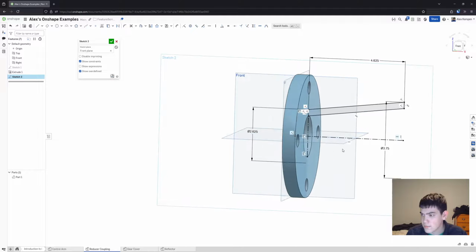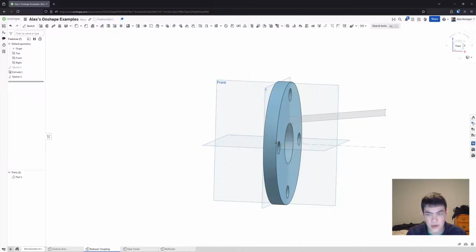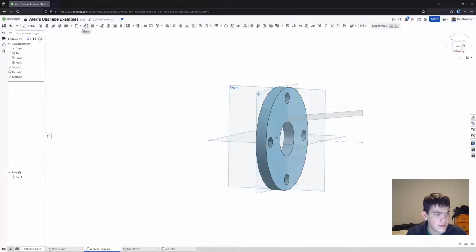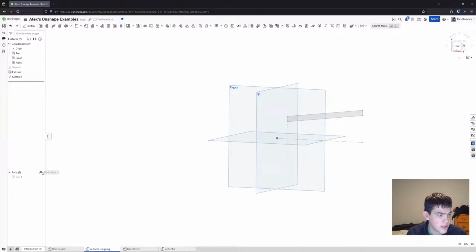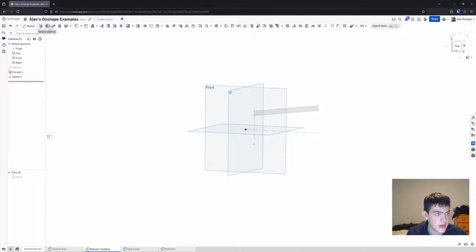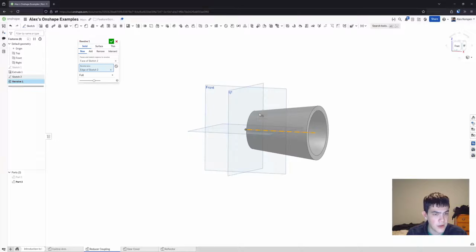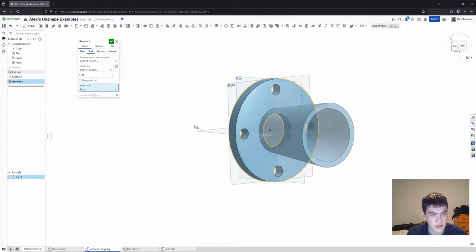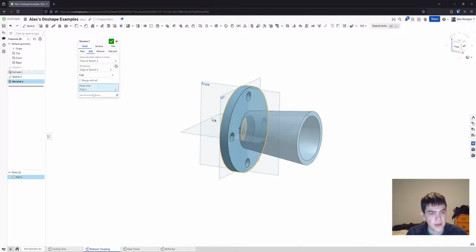Okay, cool. So this looks good, so I'll go ahead and confirm that. And now we can go ahead and revolve this, right? And once again, I'll point out, if this part were to be hidden, then when I go ahead and create my revolve, I'll just get a new part. So then I would have to manually change it to add, and when I click add, it focused my merge scope automatically, but I would have to manually select my merge scope like that.